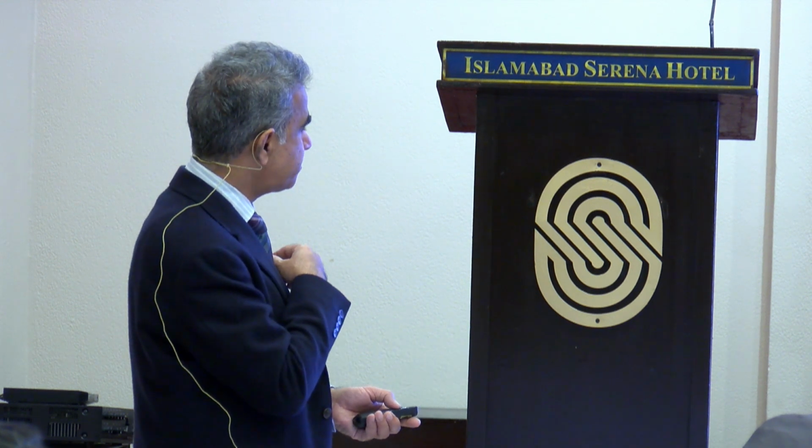Here we read 6 modes simultaneously. With this blue color, you can see the current leaving the body, going into the formation, reaching the receiving electrodes, and having different depths of investigation.